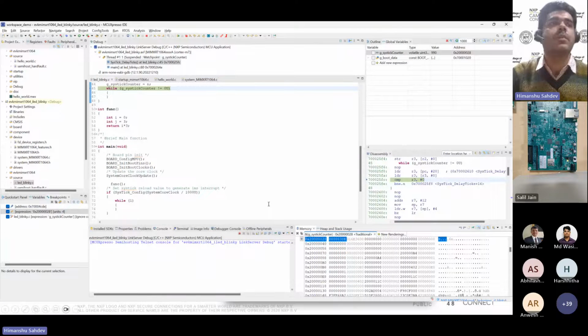So here we can see, let's say, for example, if I press the start button, we can see this value as this is basically a breakpoint and basically stops execution for you after a particular value hits. And if the value changes, it will showcase in the memory directly. So basically it's a watch window, but in the memory you can see the values getting changed. Let's see, it's DC now, DB, right, DA.